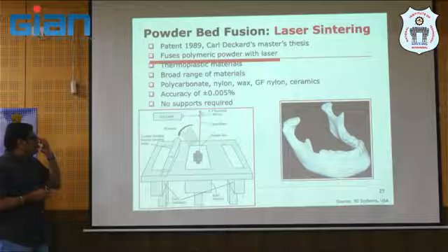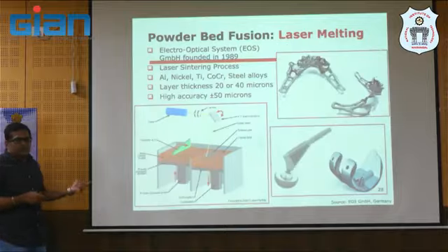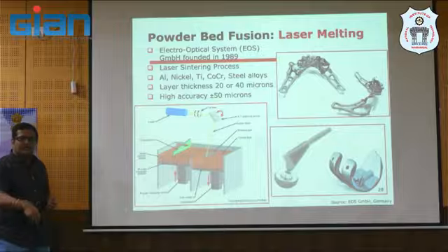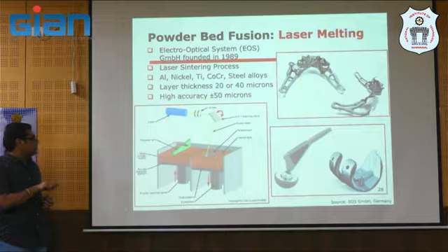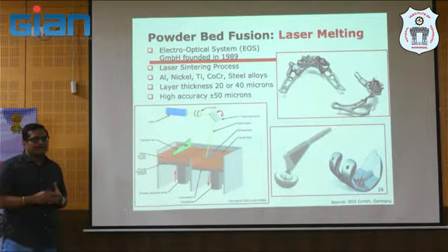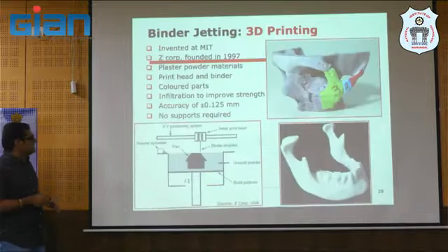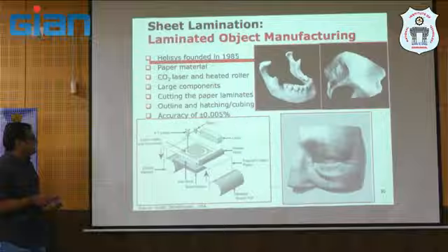So you have powder bed fusion with polymer, or even with metal. You may be interested in metal. Why? Because you are going to print some implant, maybe a dental implant, or maybe a knee, knee braces, or a femoral joint. So you may be interested in the powder bed, and that too with titanium 6-4, maybe cobalt chrome or 316L, right? Then you can very well process it here. And for multicolor, multi-material, yes, you have a binder jetting system, you can very well do that.